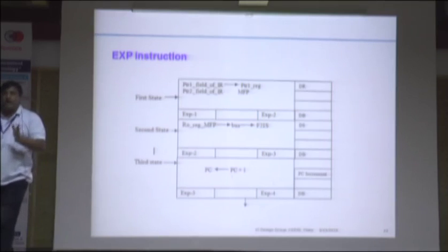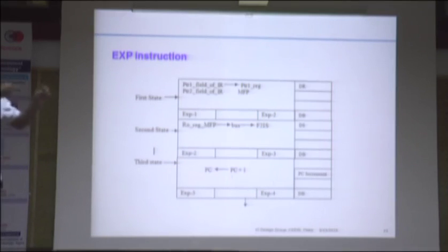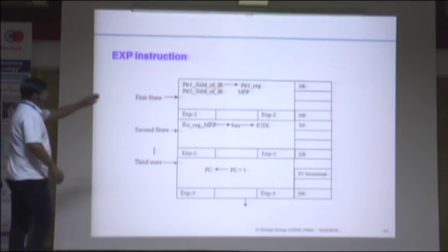So at the RTL level, every designer has to ensure that all these register transfers will be done in one clock cycle or in one state. A clock cycle, a state, or a step are all the same thing. In one state, whatever operations we do, we do in one cycle. That is what we have to capture here, all the register transfers.